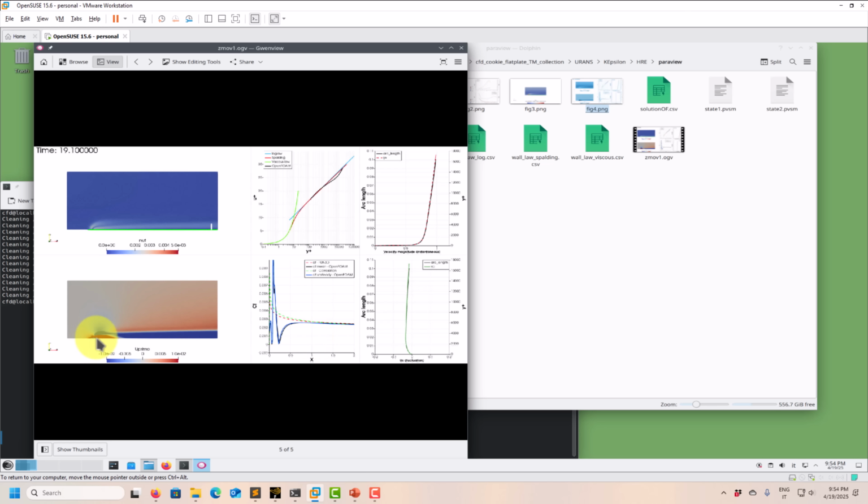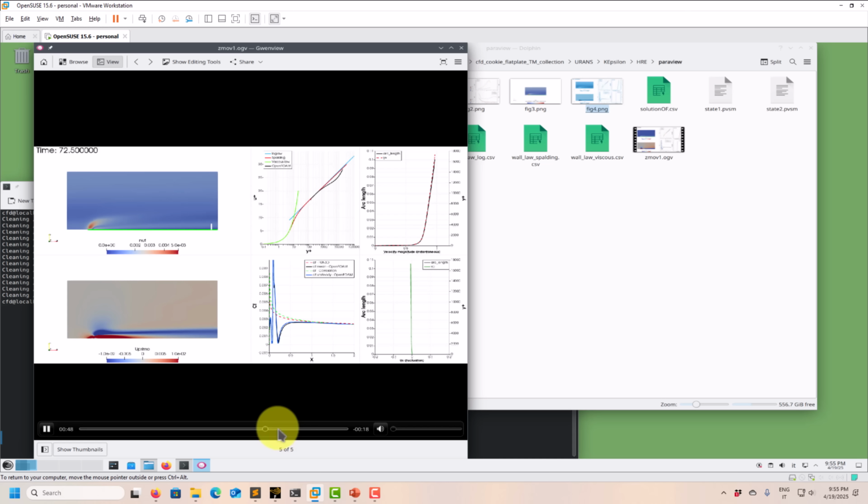Look at that, even if we are adding that fluctuation, now you have some oscillation here, but then it will match our known reference values. Probably somewhere in the middle, at 50%, 60% of the flat plate. And then this is due to the fluctuation. But look at that fluctuation, we don't see it here. We're missing that entirely due to the averaging process. Instead, if we run a scale-resolving simulation, you're going to see that. Probably with what we're adding there, it will crash. Well, we need to test that. So this is what we have with K-Epsilon, okay?